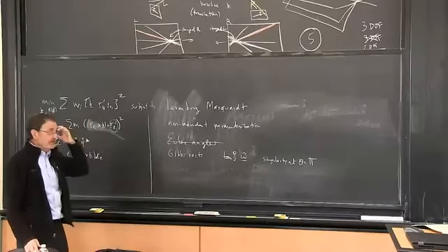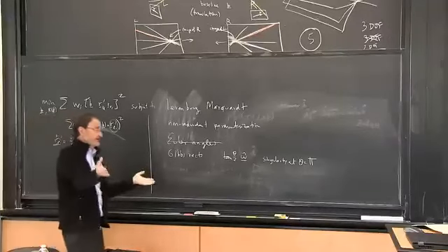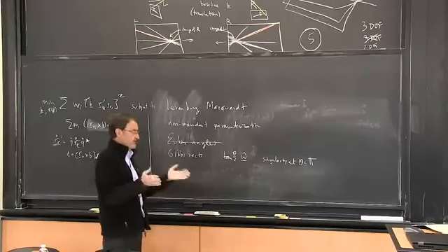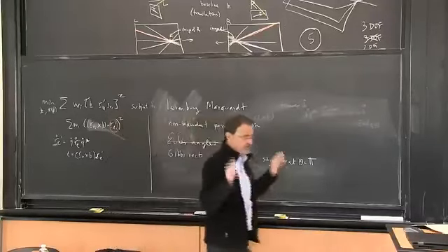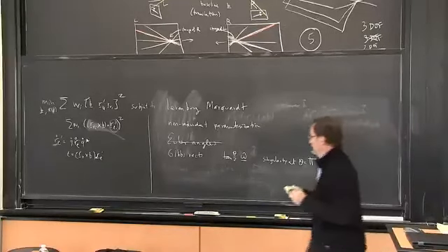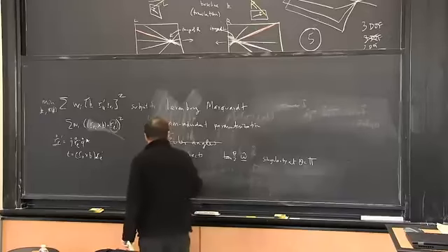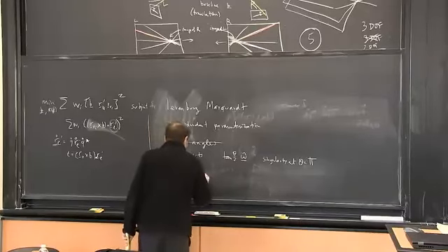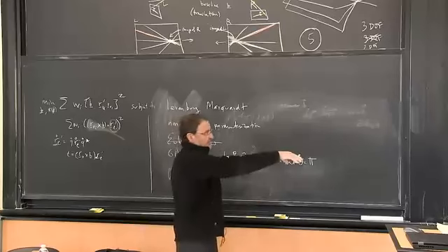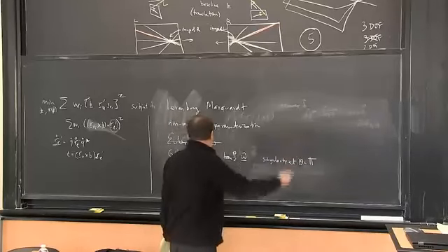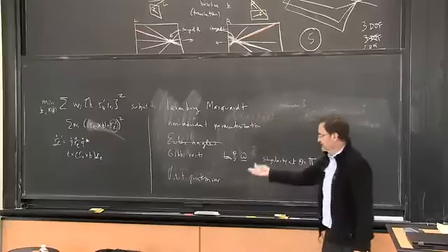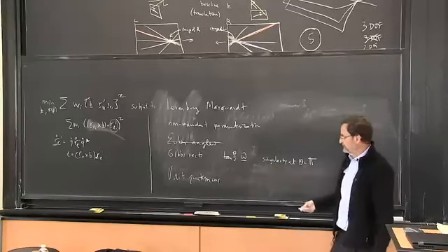And so that's a potential problem, because rotation about 180 degrees is a perfectly legitimate rotation. Now, in this particular case, you typically don't have the right camera rotated 180 degrees relative to the left camera. So in some sense, go ahead, use the Gibbs vector. It will probably work. Of course, what I'd recommend instead is unit quaternions. And we've worked out the details over there using unit quaternions. The only problem is they're redundant, right? They're 4 numbers, 3 degrees of freedom.